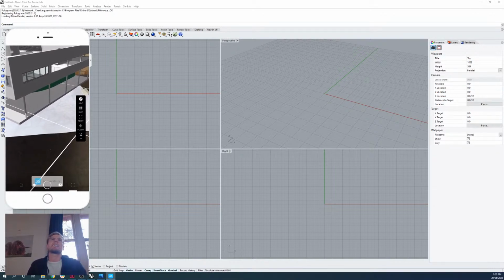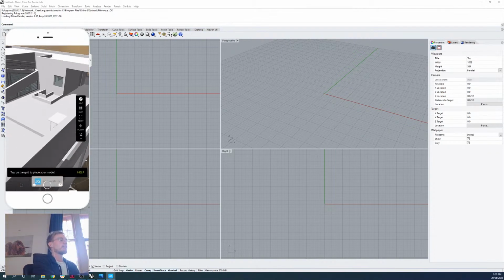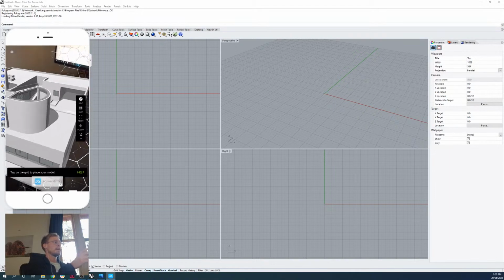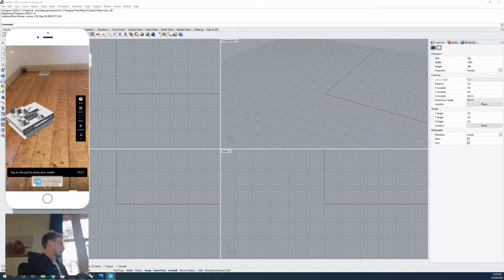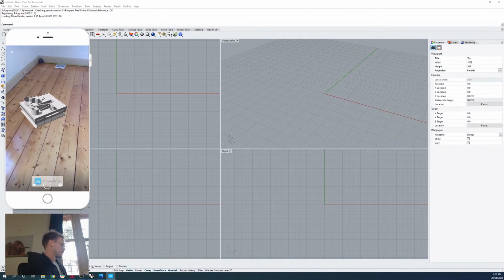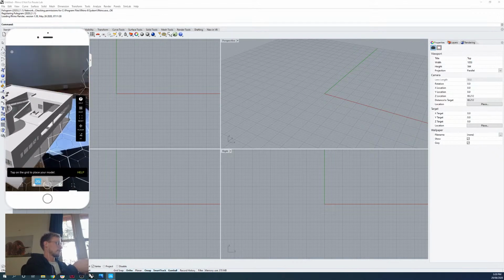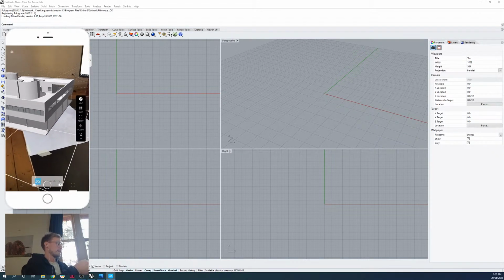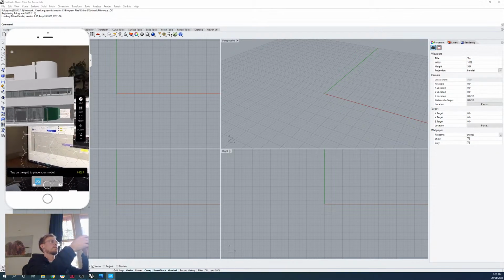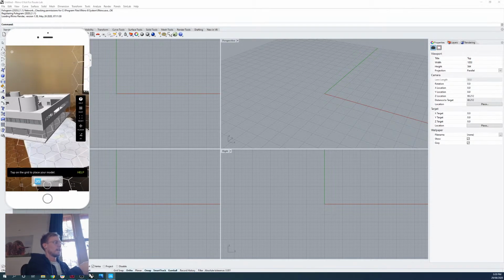This menu is going to allow us to do things like reset our placement location. So if you're unhappy with what you just did, we can easily do that. You can move your model around, rotate the model, or scale the model, or then you can register the model at a specific location in physical space. So firstly, let's try resetting our placement location. I'm going to hit the reset button, and it'll behave in a similar way to what we had before when we were getting those grids, and we could place it on any of those grids. So I could place it on another grid. If I'm not happy with it over there on the ground, I could hit the edit menu again, reset, and place it back on my desk. I could go edit menu again, reset, and place it up here on my computer screen, because I'm able to track it on my computer screen, et cetera, et cetera.